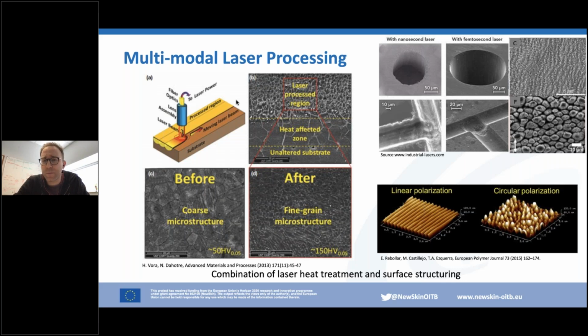With the femtosecond laser machining, we're looking at very high aspect ratio, clean, no-burr surfaces for producing these very fine structures and surfaces. This could be done either through the direct application of the laser light or through what's called laser-induced periodic surface structuring, where very fine ablation takes place and restructuring of the surface occurs due to the polarization of the laser light that's being applied.